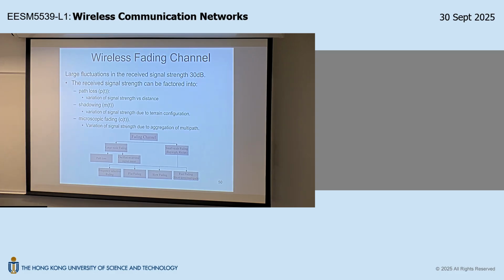Now, of course, you don't need to work it out analytically. You can even do experiment, right? You can inject an impulse and look at what is the output. That is also another way to measure the impulse response, right? So, but conceptually, even if you have to derive it theoretically, the physics domain knowledge is now completely encapsulated by this impulse response. Once you know the impulse response, the physics will be irrelevant. Is that okay? So this is why so-called channel modeling is we want to take this black box approach. Okay?